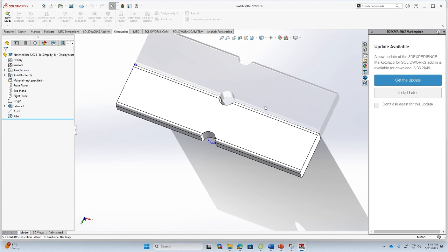For the finite element analysis, the stresses will be uniform within that element, right? The values can change on the nodes, but as far as within the element is concerned, it has to be either uniform or it has to be with a known function. So for example, it can be a linearly varying function or something like that, okay. So essentially that means your size of element will also affect your result as far as the assumption of how the stresses are changing within that element, okay.